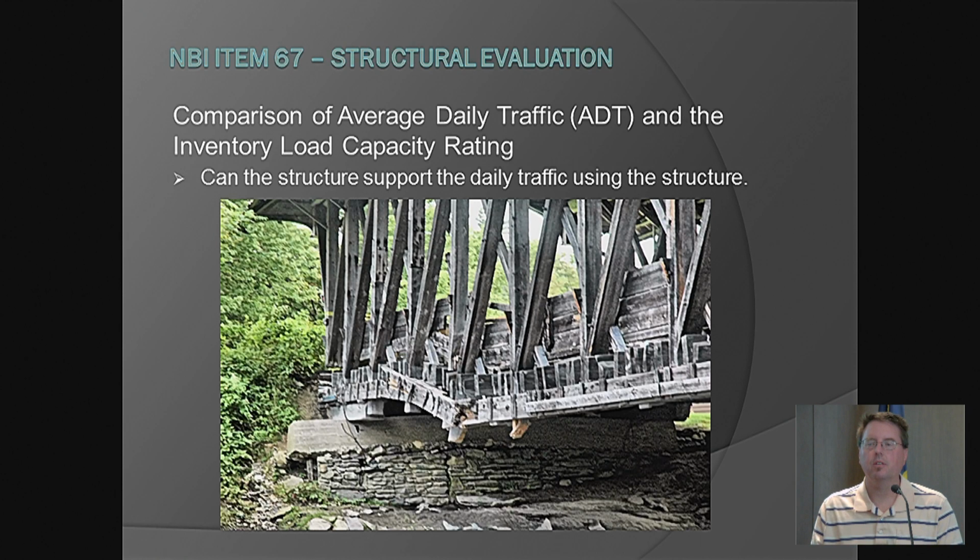Item 67 is your average daily traffic comparison. It compares with your inventory load capacity. Basically, what it comes down to is, can the structure support your daily traffic?